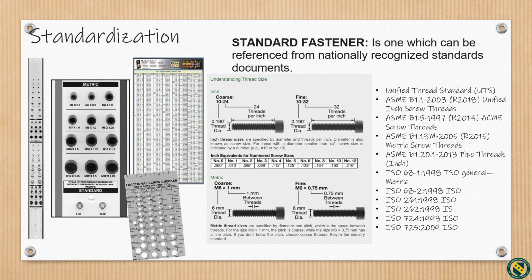The Unified Thread Standard, UTS, defines a standard thread form in series, along with allowances, tolerances, and designations. For screw threads commonly used in the United States and Canada, it is the main standard for bolts, nuts, and a wide variety of other threaded fasteners used in these countries. It has the same 60-degree profile as the ISO metric screw thread, but the characteristic dimensions of each UTS thread, outer diameter and pitch, are chosen as an inch fraction rather than a millimeter value. The UTS is currently controlled by ASME and ANSI in the United States.